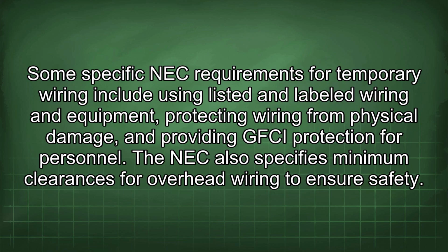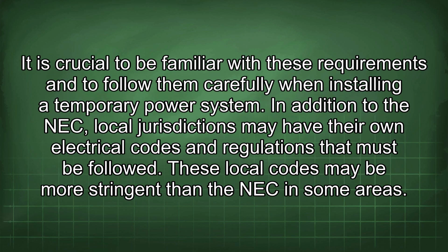Some specific NEC requirements for temporary wiring include using listed and labeled wiring and equipment, protecting wiring from physical damage, and providing GFCI protection for personnel. The NEC also specifies minimum clearances for overhead wiring to ensure safety. It is crucial to be familiar with these requirements and to follow them carefully when installing a temporary power system.